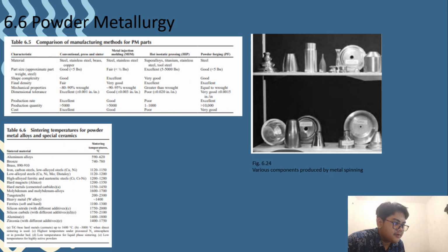Copper and copper-based powder follow iron in volume of powder used in PM fabrication. Approximately 45% of all copper powder is used in the manufacture of self-lubricating bearings. This also is used as an elemental addition in various PM parts. Another 40% is used for making hardware that requires both decorative finish as well as corrosion resistance.